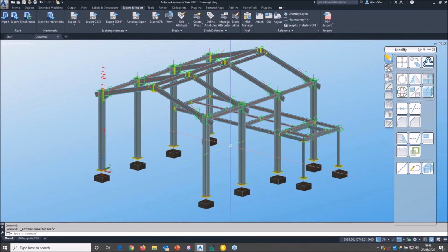This was a few years ago, and I haven't done any testing in the last few years to see what the comparisons are, but certainly he said SDNF would give a better result. The best thing is to try all of them. If StruCAD can export 3 of those formats, export all 3 and then try importing all 3, and see what you can do better. SDNF isn't quite the StruCAD native format, but it is supposed to be the best one.